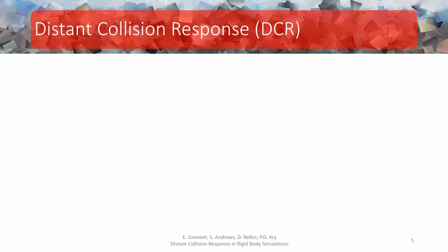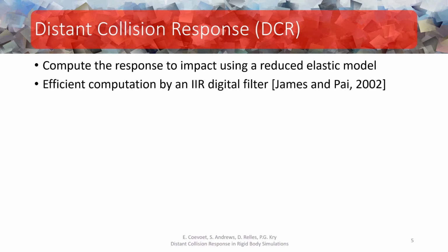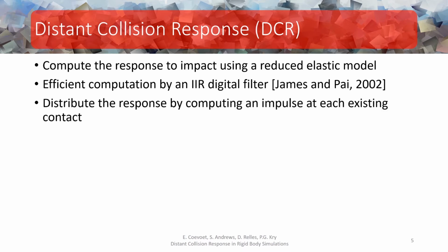And this is where our contribution lies. We approximate the vibration response to collisions in rigid body simulations by using a pre-computed reduced elastic model based on Modal FEM. To render this process more efficient, we compute the response using a digital IIR filter. The response is computed as a displacement at FEM nodes that is then rendered as an impulse at existing contacts, causing disturbances to objects already resting on the surface of DCR bodies.